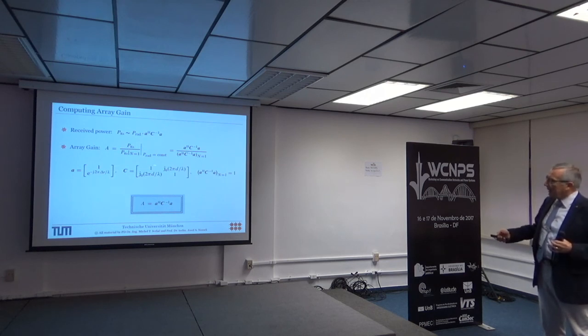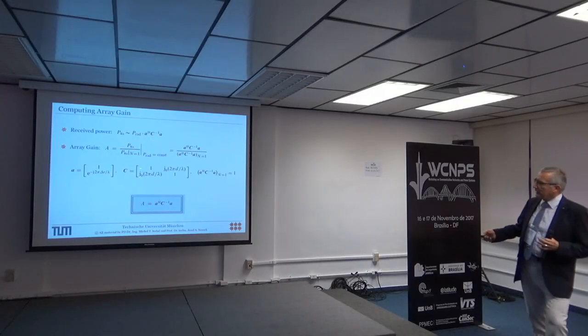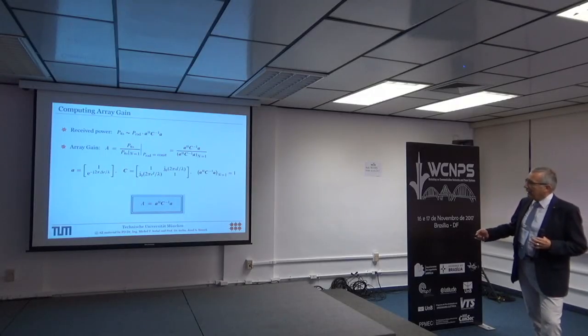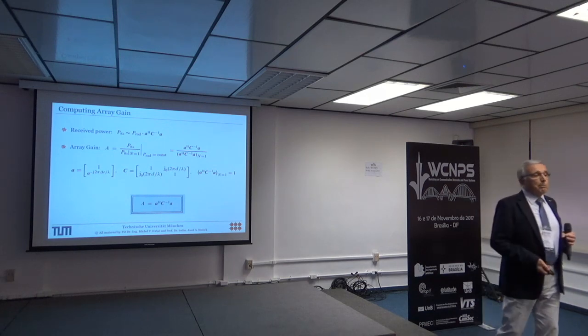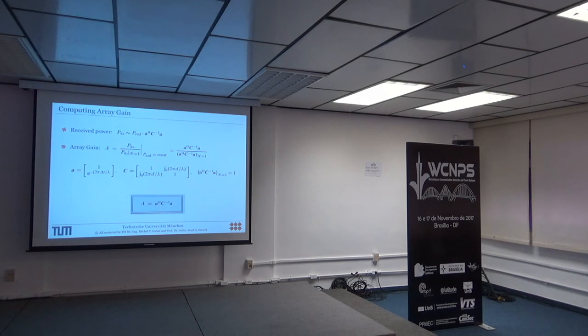Again, looking at the coupling matrix, when we talk about isotropic radiators, if I plug in that d is lambda over 2, then these two elements become 0, which means the real part of the mutual coupling is 0, and then it's almost as if the two antennas are not coupled. And then it's the Euclidean norm, because the matrix in these quadratic forms is then an identity. But that is a very specific case only. This is not the general answer.